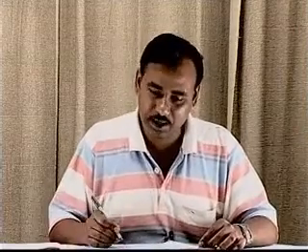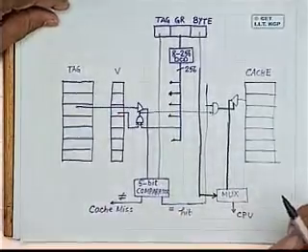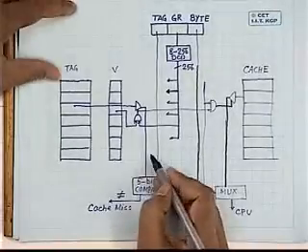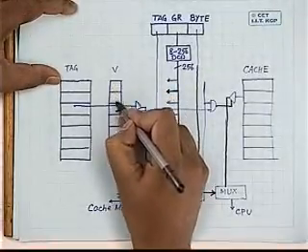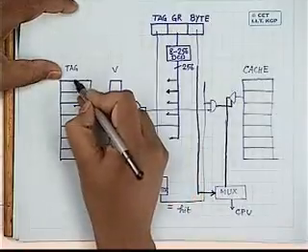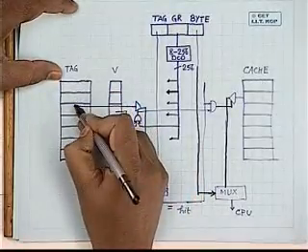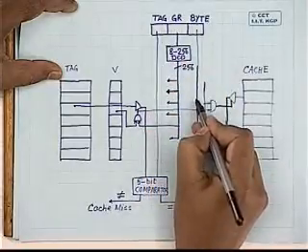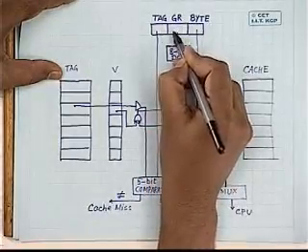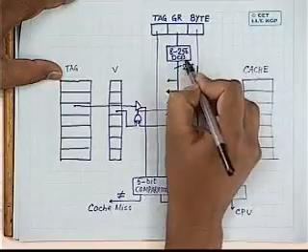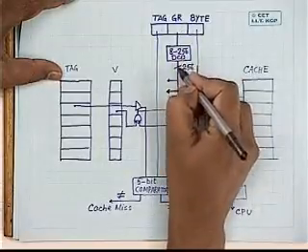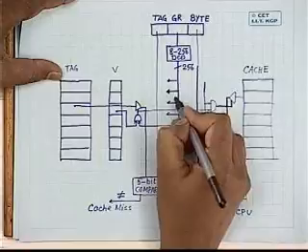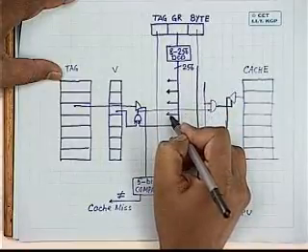Okay, and I hope you can draw a similar schematic diagram for this two-way cache memory or even for an n-way cache memory. In that case, what you have to do is this valid bit will be replaced by two valid bits. The tag memory field will also be replaced by two tag memory fields. This part will remain the same because the group identification, which is 8-bit, has to go to the 8-to-256 decoder. Out of this, I'll have one of the outputs active.